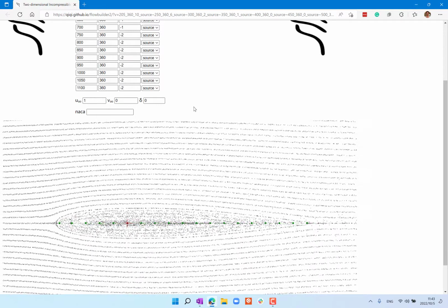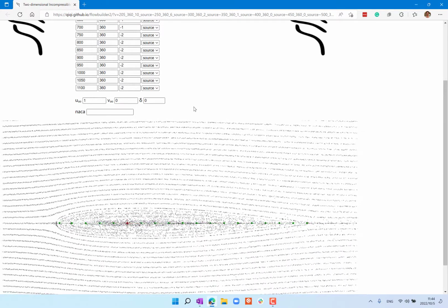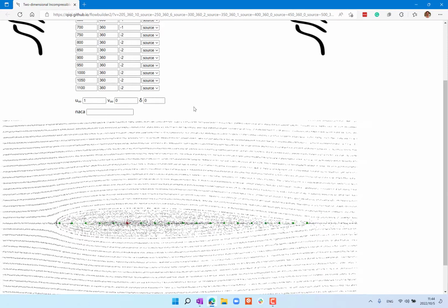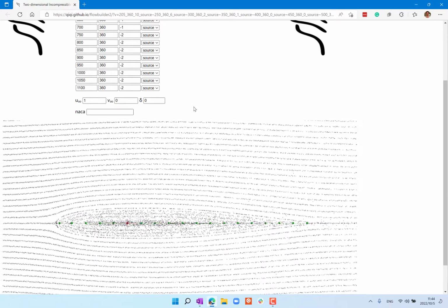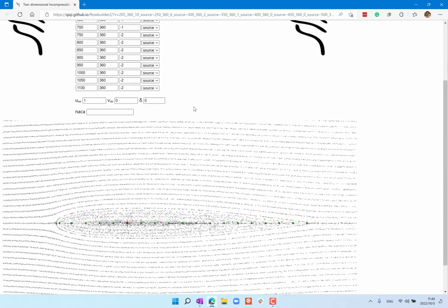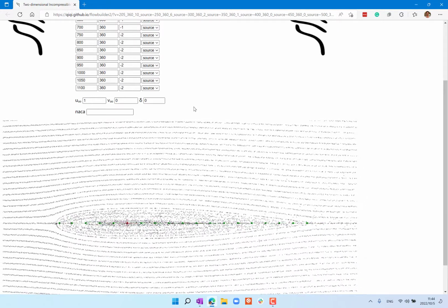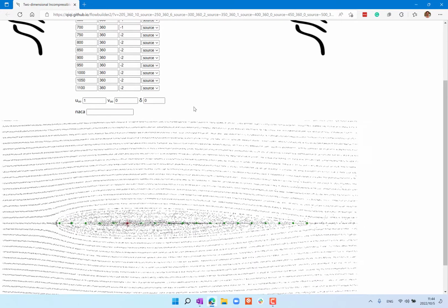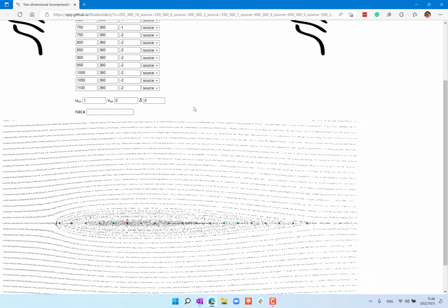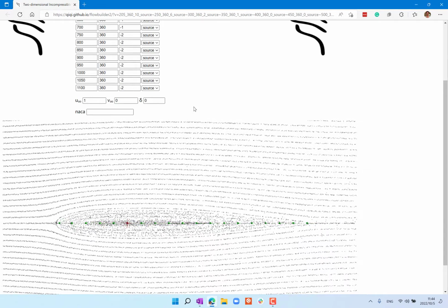That makes sense, because when you have flow spewing out, it makes the portion bounded by the two streamlines that come from the stagnation point wider. And whenever you have things sucking flow in, you make the stream tube narrower. That's basically conservation of mass. So if you draw a control volume that ends over here, how thick the airfoil is is proportional to how much artificial mass you are injecting into the flow field. Okay, any questions regarding that?